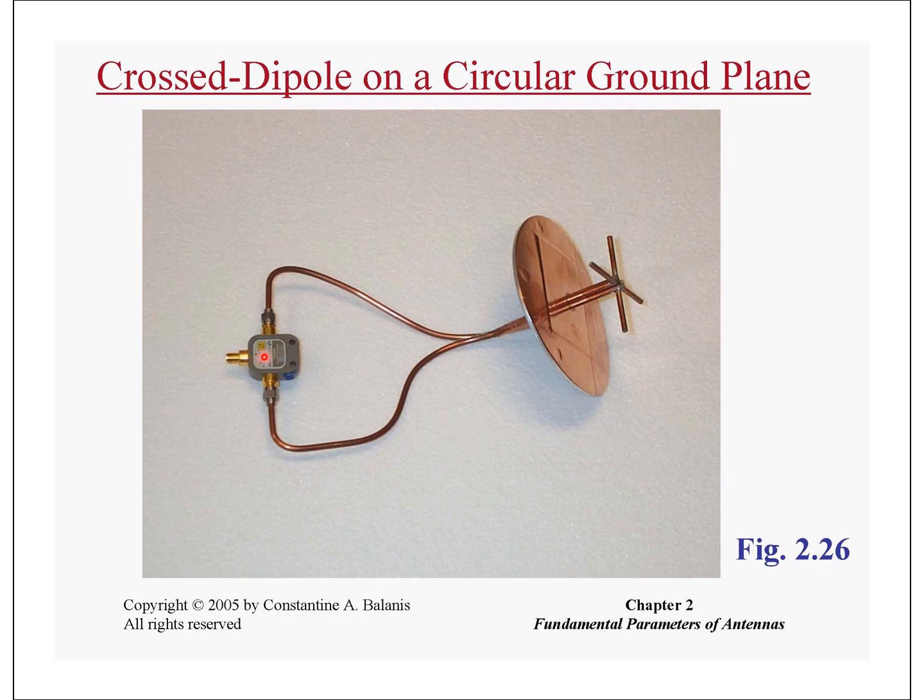So the power is split into two equal halves, and then it goes to the cross dipole antenna. Here the ground plane is also shown. The ground plane is connected in order to get maximum gain, to increase the gain of the dipole antenna. And you see that each dipole gets equal magnitude of power. That means one dipole is along the x-axis, so the value of Ex will be equal to Ey, and that is the first condition for circular polarization.